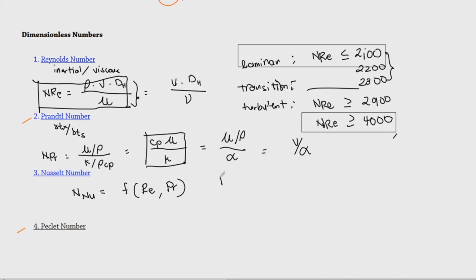So if we're considering a diameter, we have conduction over convection, and we're considering the resistance. Remember, before we used to solve the resistance of conduction, that is over k, and if this is the thermal conductivity, then the reciprocal would be the resistance. And then we divide that with, of course, the resistance to convective heat transfer, which is the reciprocal of h.